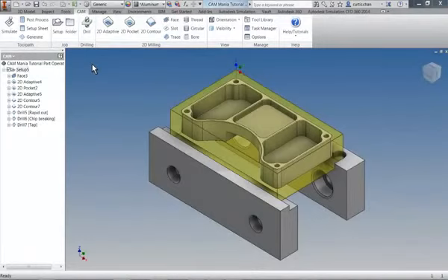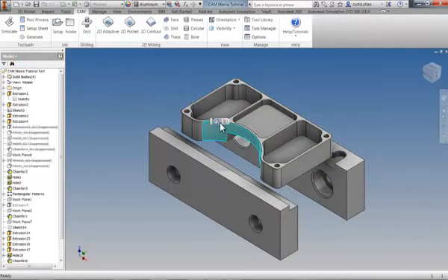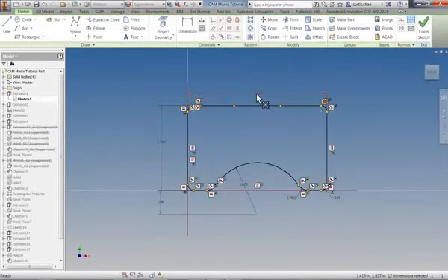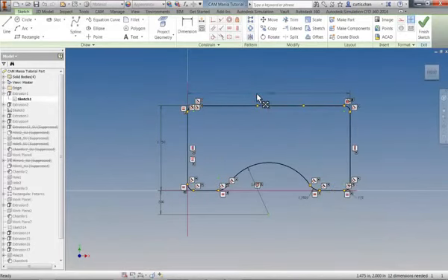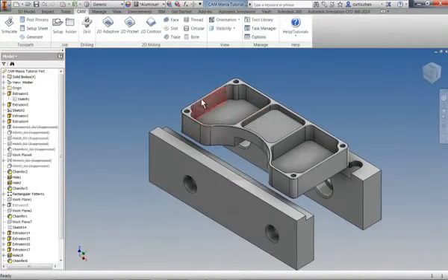So you've been issued a design change. Let's work through the processes of updating the part in toolpaths. You'll find that by leveraging the parametric abilities of Autodesk Inventor, this process is going to be quick and painless. Select an outside face of the part, edit the sketch, and change the width of the part to 3.5 inches, and accept. Finally, in the model browser, unsuppress the added features, and when we return to the CAM browser, we